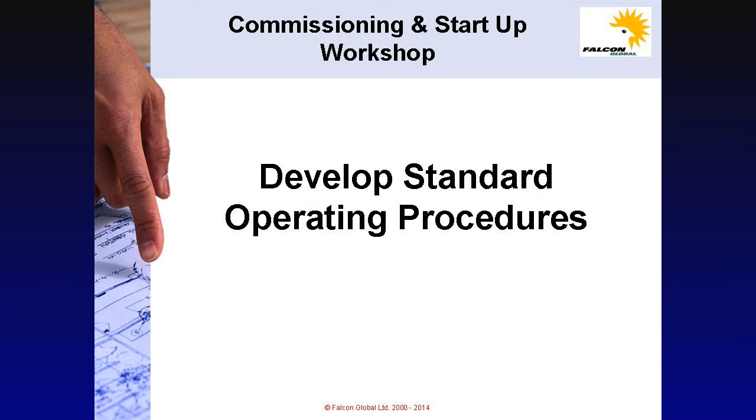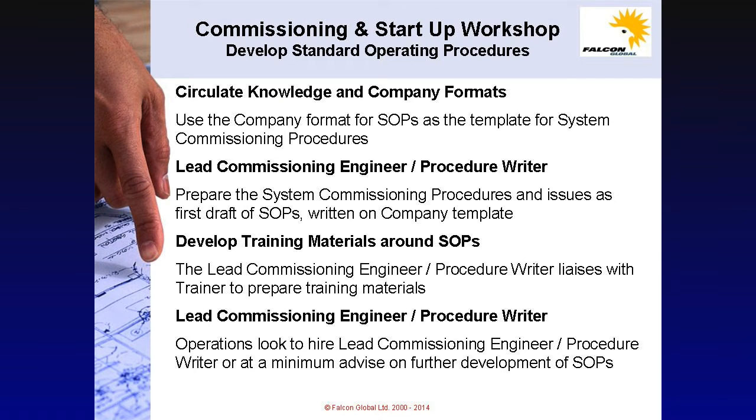Develop standard operating procedures. Circulate knowledge and use company formats. Use the company format for standard operating procedures as the template for system commissioning procedures. Involve the lead commissioning engineers and procedure writers in this process.